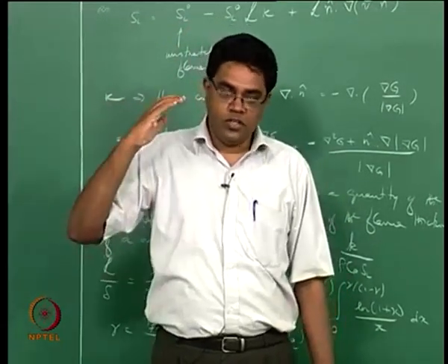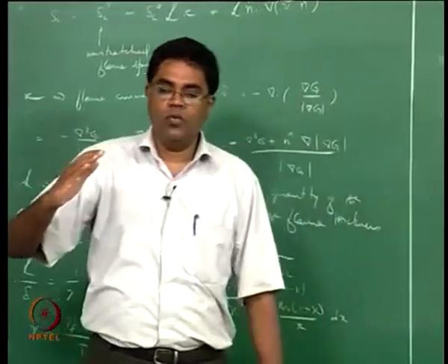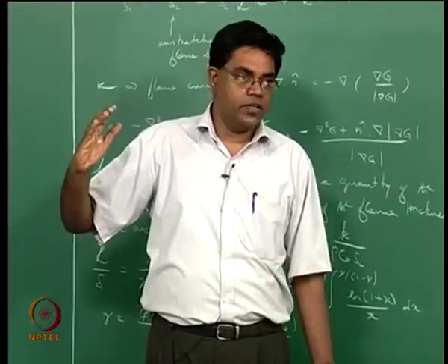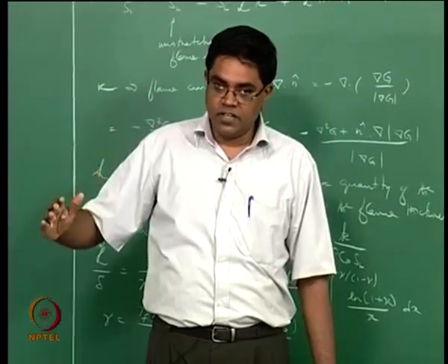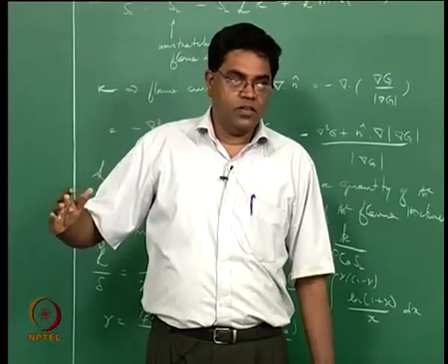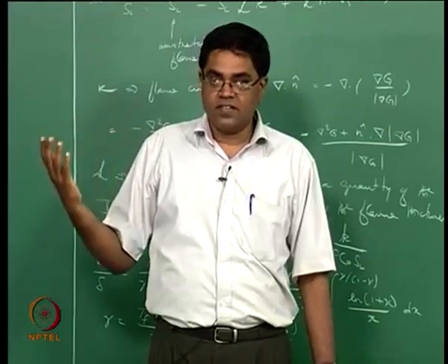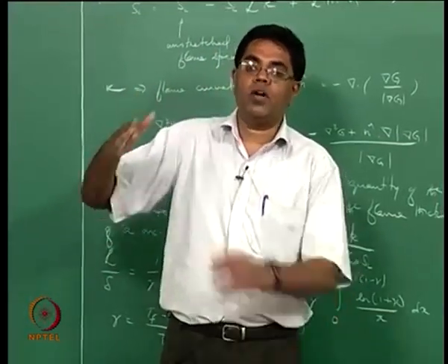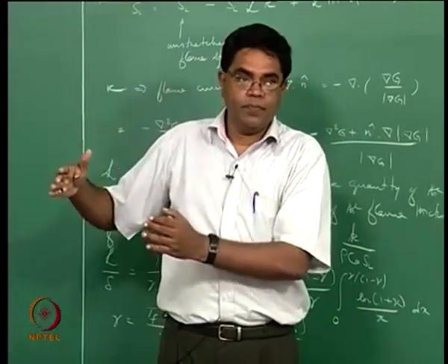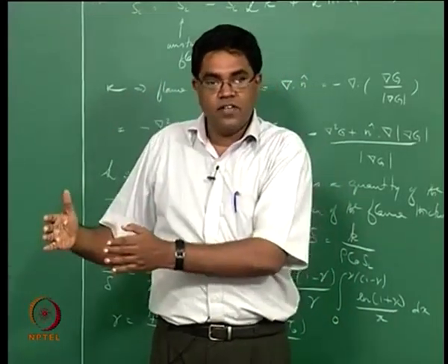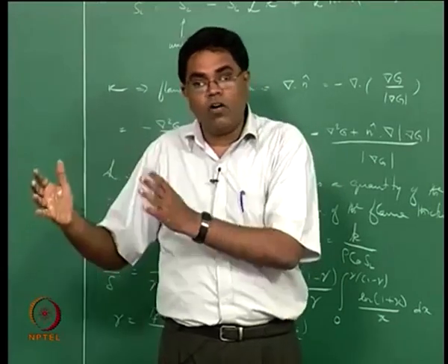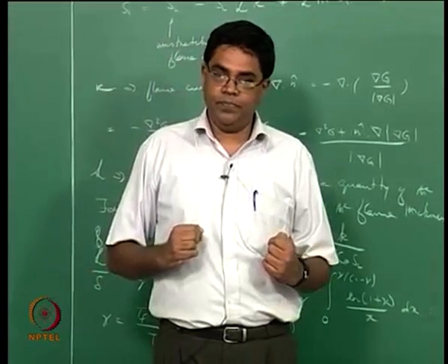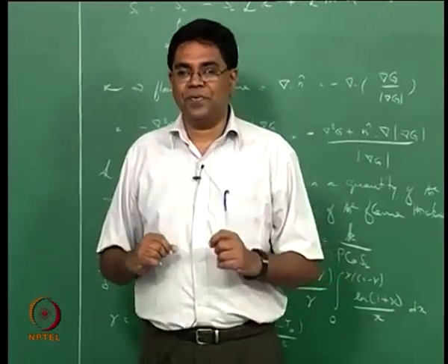Of course, within the framework of the G equation, we don't bring into effect the thickness of the flame. So it's as if the flame has a thickness, and we are basically saying that S_L is a constant, it doesn't change, and therefore we don't have to worry about a varying thickness of the flame near the base, or a varying flame speed as we approach the base. But none of these things is true.